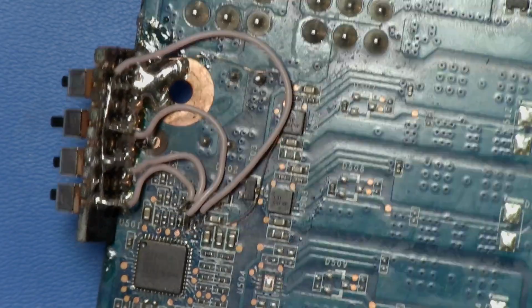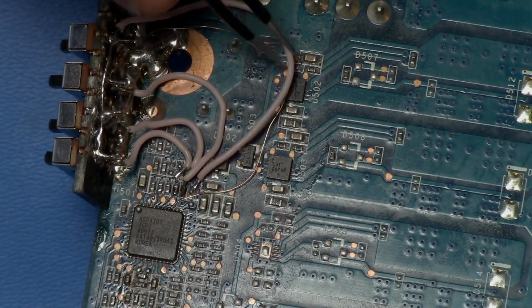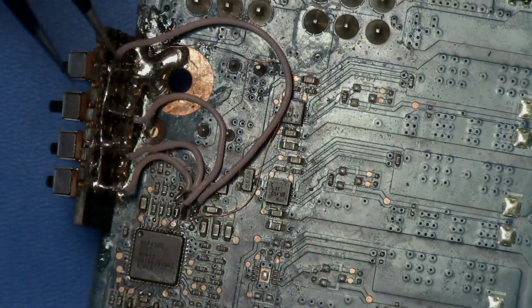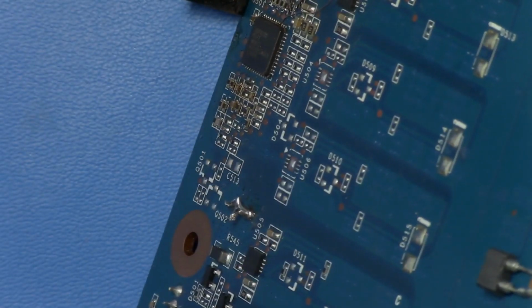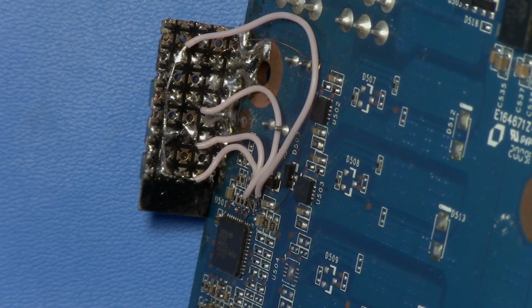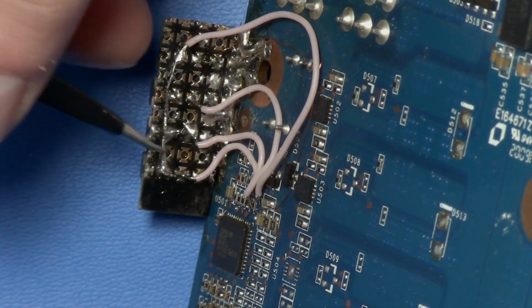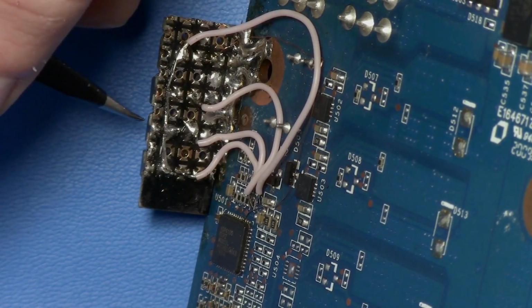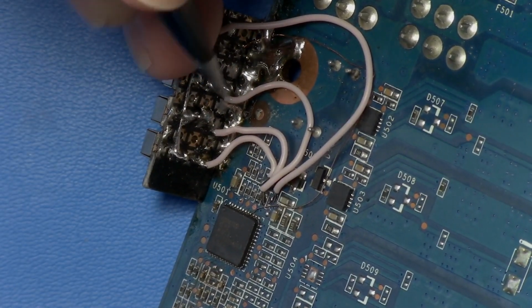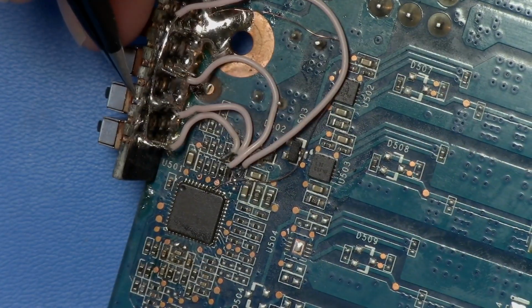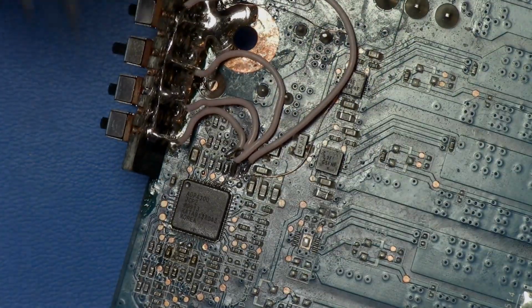Yeah, basically from there you can see this is actually this wire here. Here's the 3.3 volts. There we go. Kind of hard with this. This wire goes along the top. That connects 3.3 volts to one side of all of these switches, and then the middle pin is the one that's switched either to 3.3 volts or just to the floating side. The floating side doesn't matter.